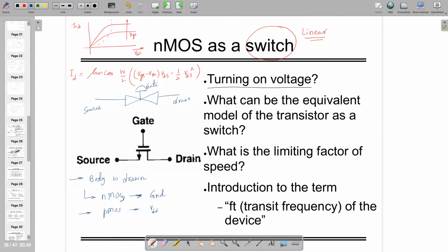If the gate voltage is high enough, higher than the VDS sat line, the potential at which the transistor goes to saturation mode or linear mode, that governs this entire device. If that is sufficient to keep it in linear mode, you can have Vs equal to Vd, right?